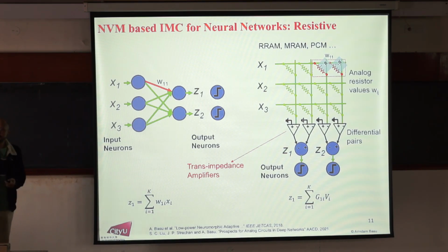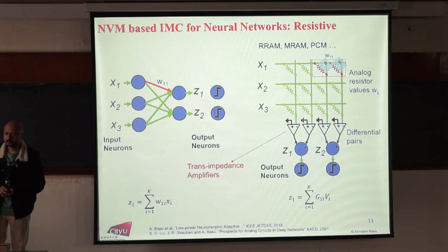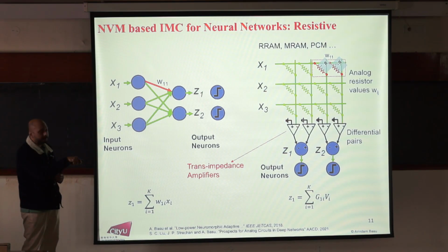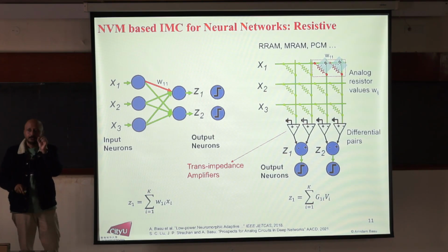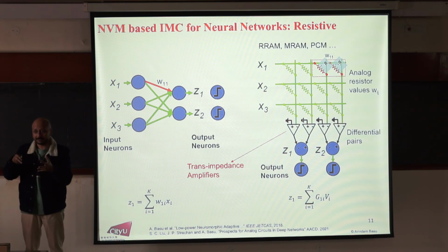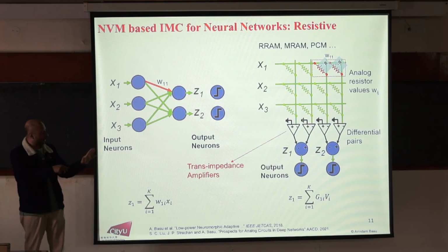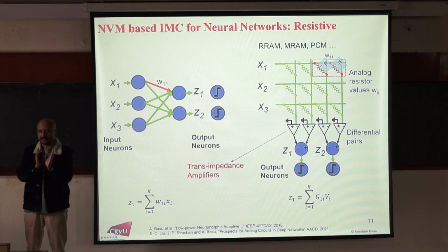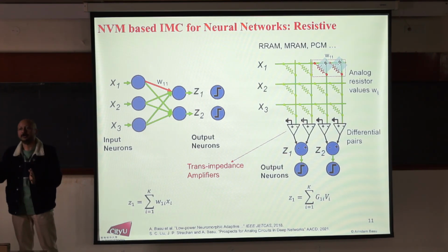Very, very true. So that's a circuit question. Generally, when you have a transimpedance amplifier, what happens is the capacitance on this line is generally pinned to a value. The transimpedance amplifier does not let the voltage change. So even if there is a capacitance, it's not going to get charged or discharged. But of course, it's limited to the finite gain of the amplifier. Yeah, of course. So all of those will be there. So here I'm not going into the dynamics at all. I'm assuming everything is settling. So the time that I'm giving to the circuit, allowing the transimpedance amplifier to settle.